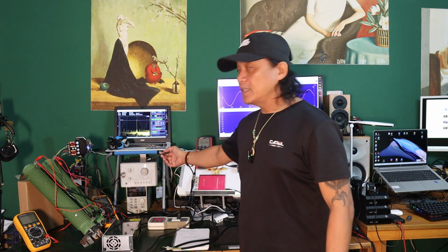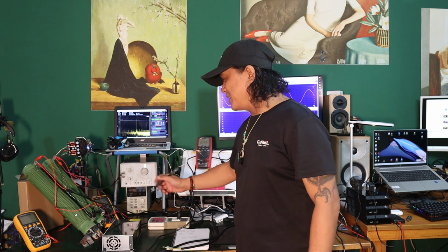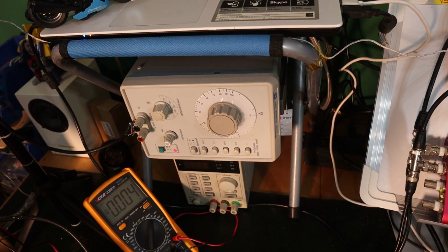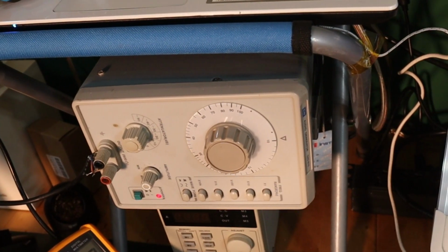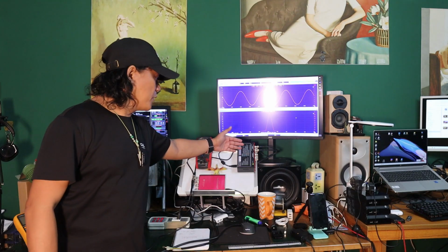Let's see the source of audio signal, the AF generator, the audio frequency generator. I mentioned that it is traditional because it is traditional by itself, not coming from the PC base. Both of these equipment, the DSO2820E and also the QA401, have the internal AWG, the so-called arbitrary waveform generator, but I did not use that for a simple reason, again, the grounding system. And this really makes it complicated.